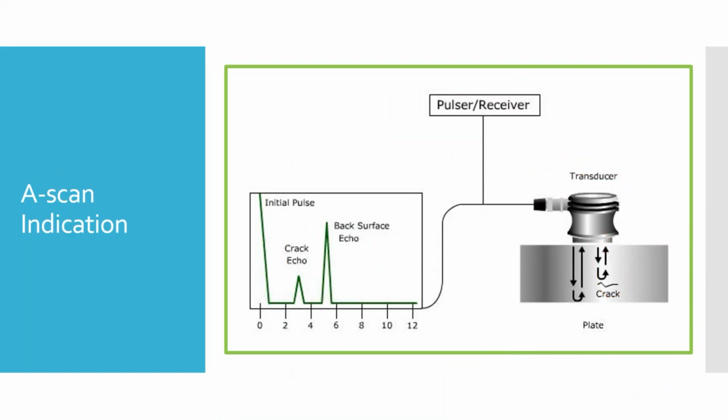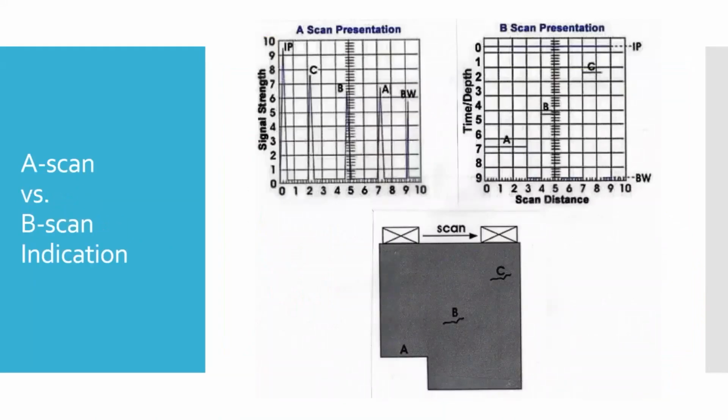And so that's what we'll be looking at with our testers in our lab. B-scan is where now we can get a side profile. The key is, we've got essentially the same part here with an A-scan on the left and a B-scan on the right. It gives you depth over a distance. But in order to do a B-scan, we have to be able to translate movement of our probe to movement across our screen, from left to right here.